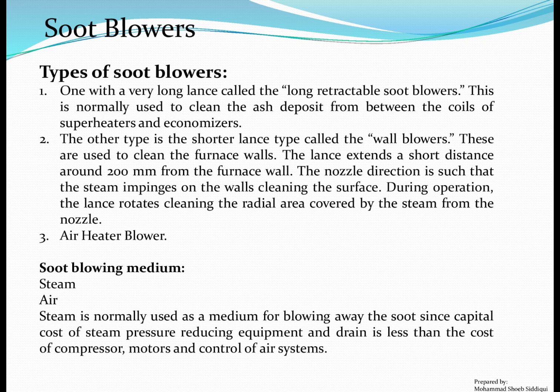Soot blowing medium: steam or air. Steam is normally used as a medium for blowing away the soot, since the capital cost of steam pressure reducing equipment and drain is less than the cost of compressors, motors and control of air systems.